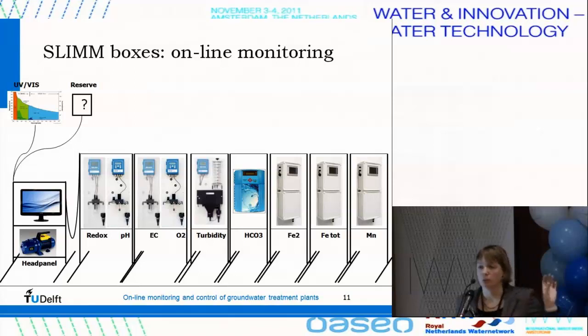the processes we are monitoring are mainly processes that are taking place in a treatment plant. So we have redox, pH, conductivity, total hardness, bicarbonate, calcium, iron, and manganese. And what we're doing right now is that we're monitoring the treatment processes individually in time, and then with that information gathered, we're going to calibrate the models on. And based on those models, we can develop the soft sensors.